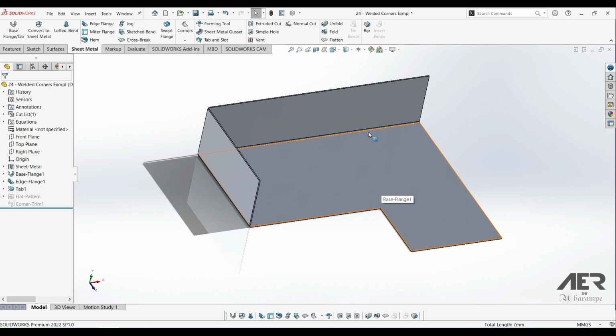If we want them in the folded up model, we can either add them manually, like we just did, or we can use the unfold tool, and then collect all of those bends, and then choose the fold tool to fold it back up again.